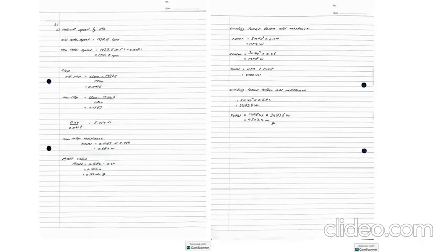Okay, for the last question is to calculate the resistance that is added to the rotor circuit that reduced the motor speed by 8%. So the speed is reduced by 8% from the old RPM value, 1437.6 RPM. So we just multiply by 1 minus 0.08, where we get the answer, the new rotor speed is around 1322.6 rpm.